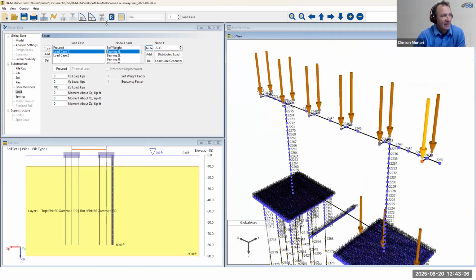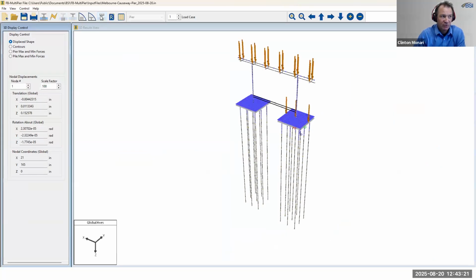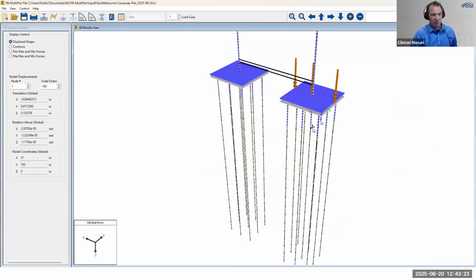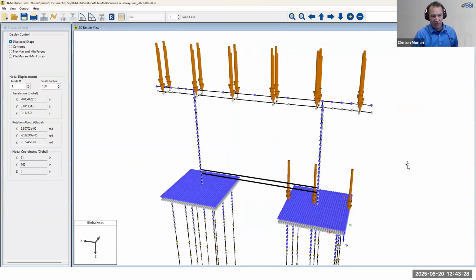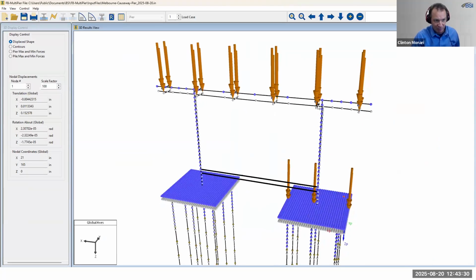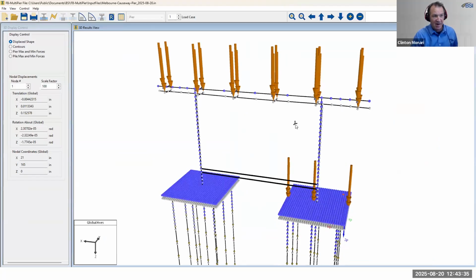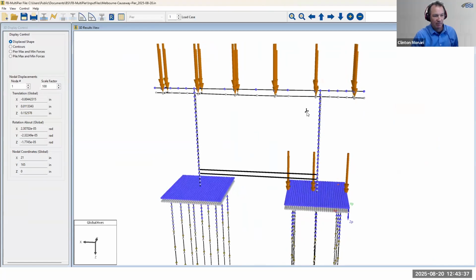So that's the analysis that we just ran, and we got convergence. These toolbar buttons to the right of the analysis lightning bolt are your entry points to the different result side views. So we're going to jump right to the 3D results. If I click the 3D results toolbar button, what we get is a drawing by default that's showing both the undisplaced model, which is the top one, and the displaced model, which is the bottom one. And we see the loads there as well.